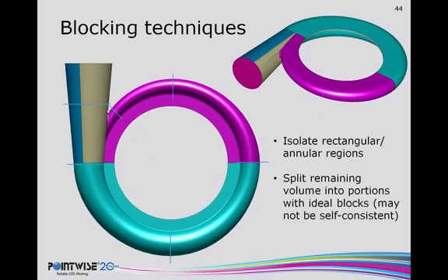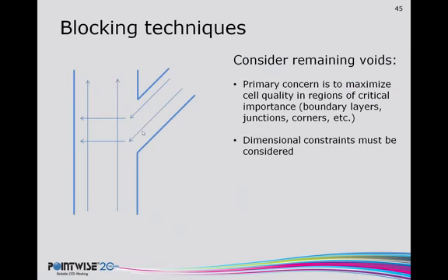But for instance, in this case, because the cross-sectional area of the scroll at this point and near the outlet here is such a disparate scale, we're really going to need a different topology. That's not going to work, and additionally, that's not going to allow us to resolve these feature lines in the model that we really want to keep. And then also you can weigh in dimensional constraints, etc. And that may rule out a couple of your topologies.